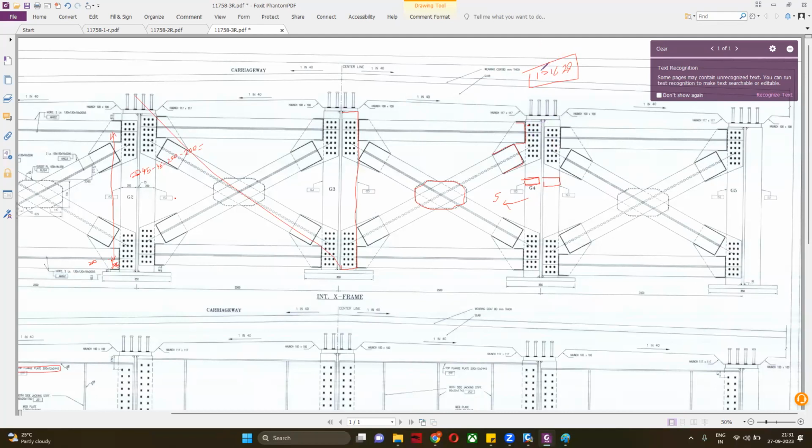We need to provide 12 mm for our web, then we need to provide stiffeners of the same or maybe lesser thickness. Generally lesser plates are available. Then even our stiffeners will try to buckle, so we need to provide longitudinal stiffeners also. You will see longitudinal stiffeners in very few projects, but we can provide them.